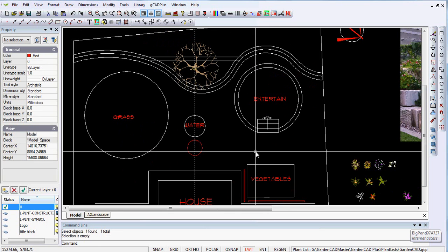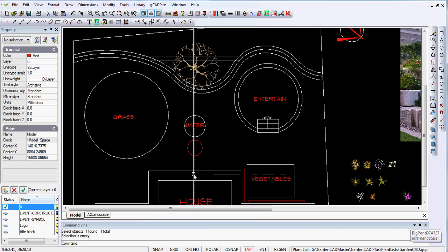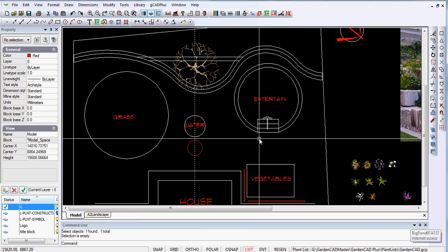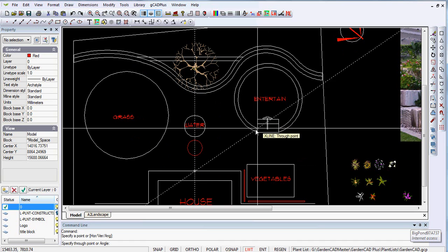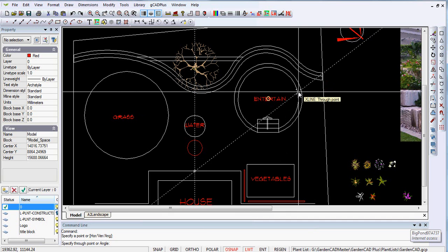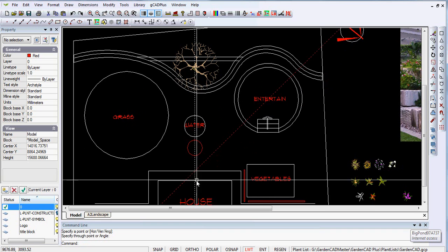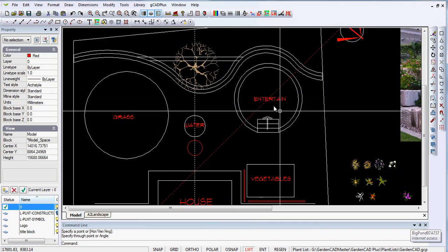Now, as I look at that design, to have someone walk from a house, maybe through some sliding doors out onto a pathway, and then move across some paved area through here to those steps, the steps themselves are wrongly positioned. Let's draw a construction line from the intersection of these two here to the centre of that circle, that arc, that denotes the exit from there, the entertaining area. It'd be much better if we moved out, stood here, and the steps led us to the entertaining area.